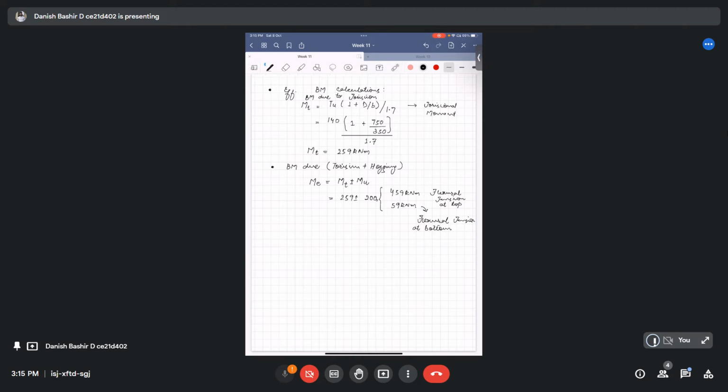Just like this, for example, this was the beam section. It was subjected to this hogging moment. Okay, so this part will be in tension. This would have been in compression, but there was also torsion present. This torsion added in such a way that the equivalent moment and the equivalent bending moment both caused flexural tension here as well.